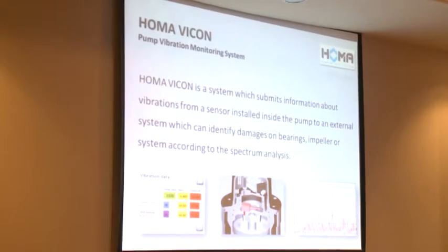So there's an acceleration sensor. I don't know if you can point it out here. The acceleration sensor is inside this box, which is directly connected to the pump casing. This acceleration sensor can determine certain frequency spectrums which are given from the motor and from the hydraulic, from the impeller, and this can be determined accordingly, so where the vibration, where the failure